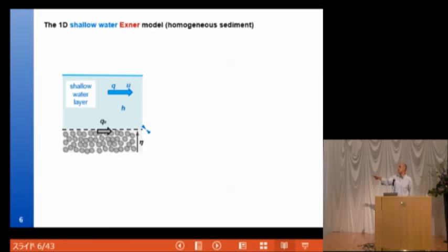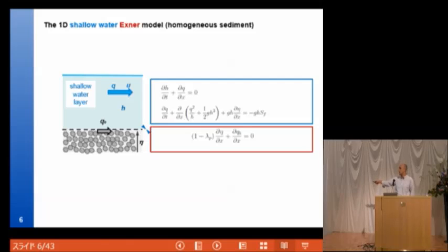Before starting the analysis, I will analyze the shallow water Exner model, essentially. Here are the governing equations of this problem. In 1D, you have three equations, essentially. This is the Exner equation. These are the two shallow water equations. This model is used for homogeneous sediments.